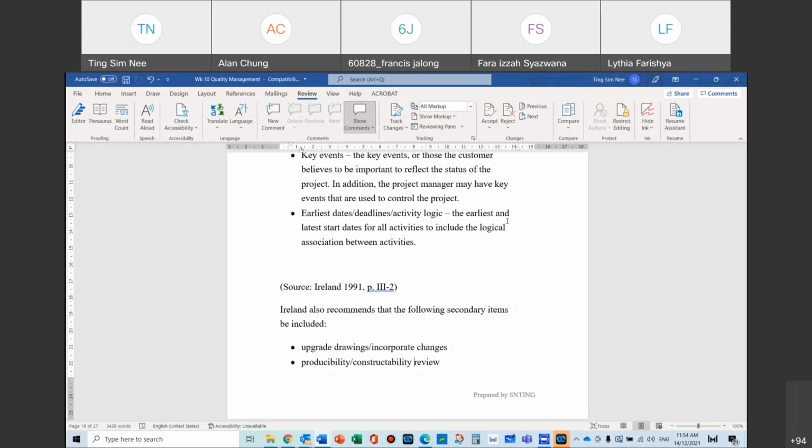how frequently do you monitor, how frequently do you test, you know, every batch of concrete comes in, slump test, how many times, test cube, how many. This is all about planning to monitor and control. So that QC is about controlling, actual control.